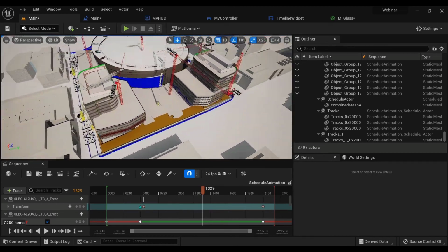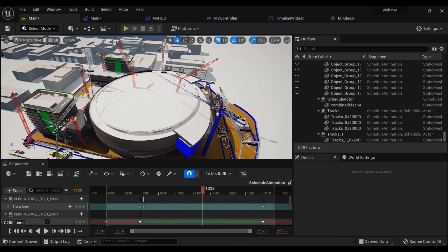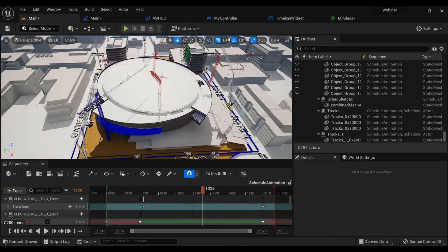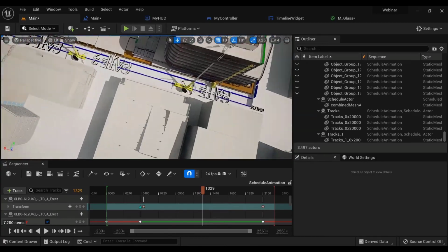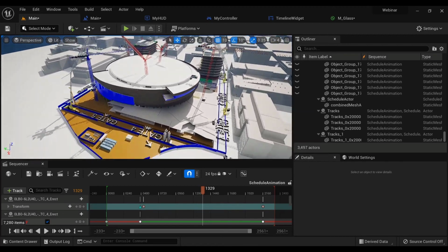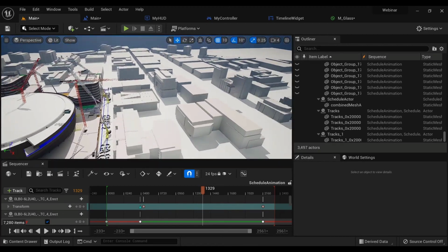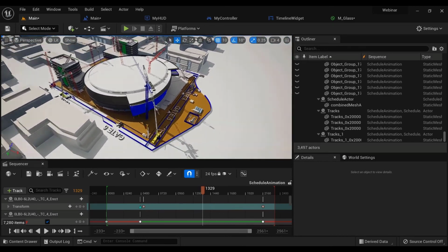With that done, really it's up to you to customize your iTwin's geometry and use the data through any data prep recipes to get your iTwin and all your engineering data and connected models into Unreal here, and just use the tools in Unreal to do whatever your heart desires with this stuff.